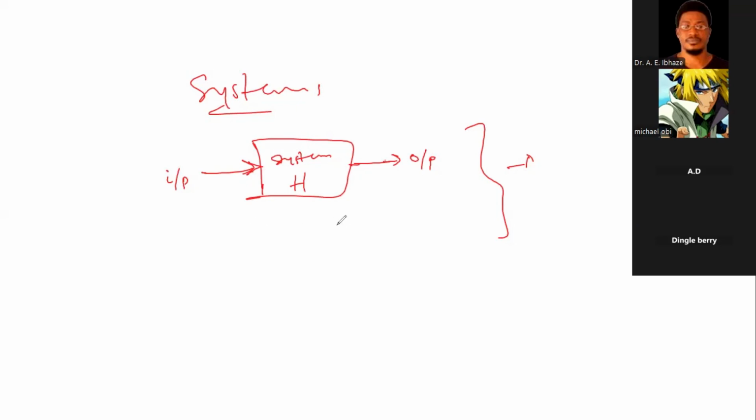And for us to do that, Nyquist says something, okay? So we have to sample at a particular rate, twice the maximum frequency. And then there won't be the aliasing and all of it. But we'll come to all of those things later, okay? But let's take it in bits, okay? Just the same way we made mention of the broad categories of signals, we also have that too.